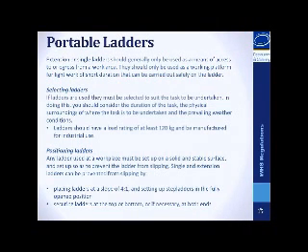Portable ladders. Extension or single ladders should generally only be used as a means of access or to egress from a work area. They should only be used as a working platform for light work for short duration that could be carried out safely.